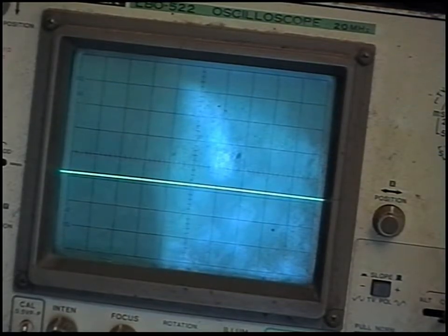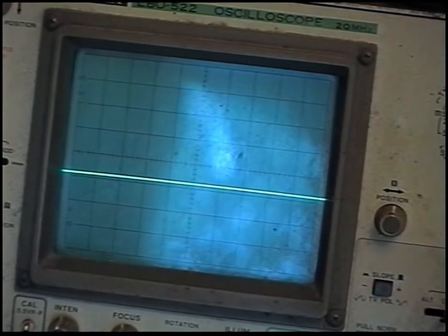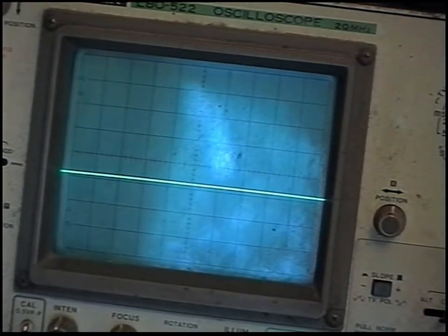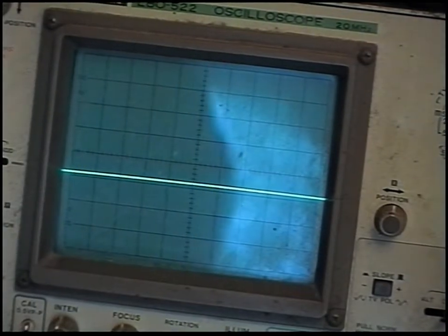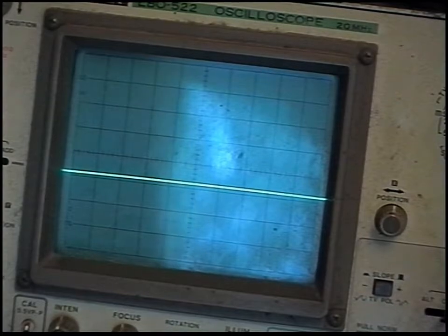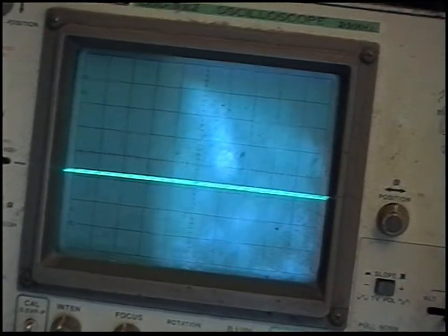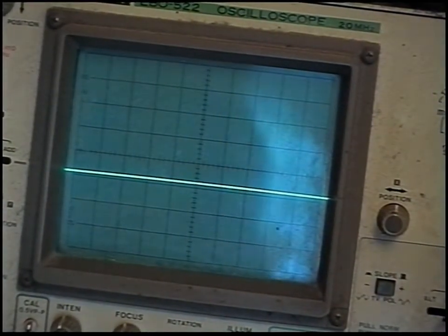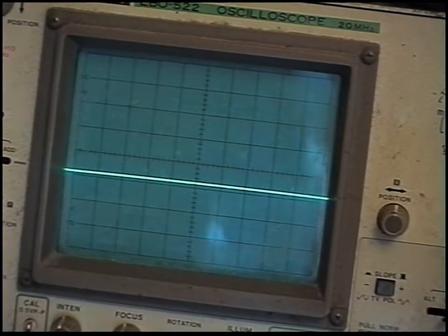that's one side, that's the other side. There's a note there. That should be 64 volt peak to peak waveform, and that should be 29 volt peak to peak, like a ramp, you know, a sort of saw wave deflection signal there.